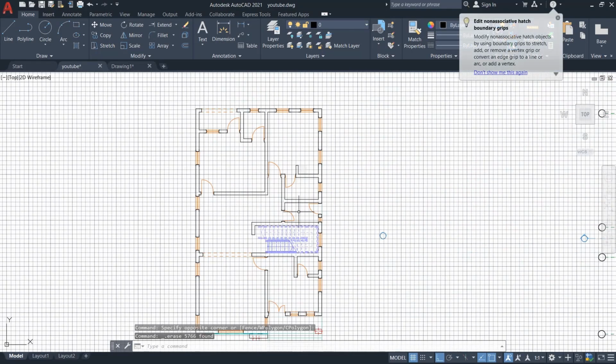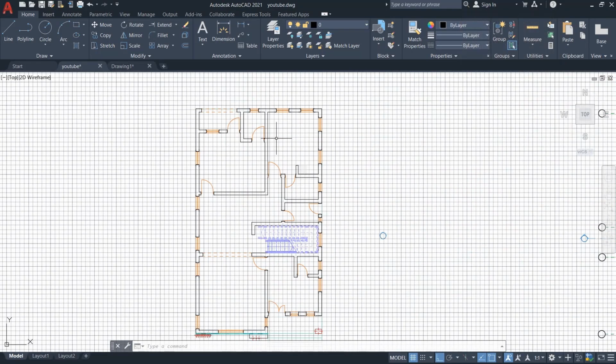Okay. So I purposely left the doors here and the windows. I like leaving them so that if I'm doing a column placement and my column is on a window, it can be moved without shifting the window. I always encourage that to keep the aesthetics of the buildings, work hand in hand with the architect. So we move on to grade.